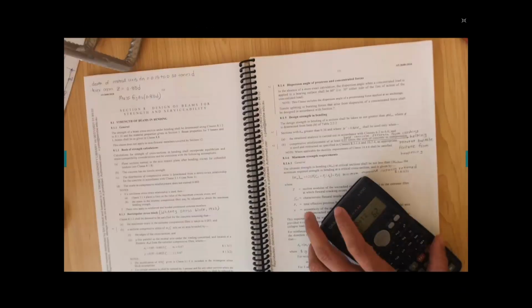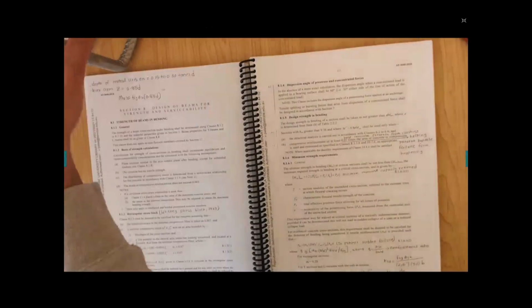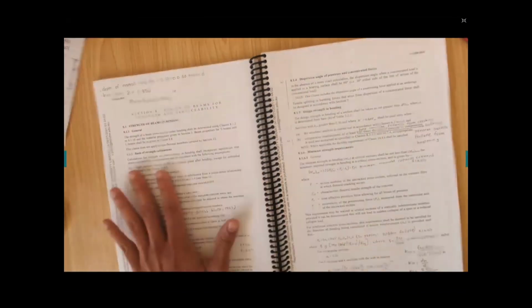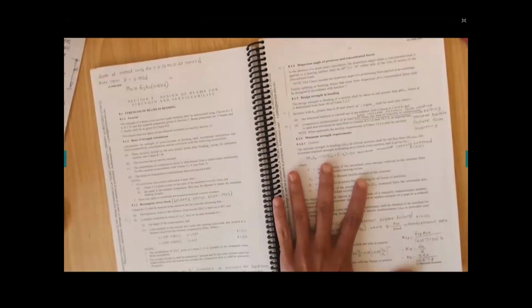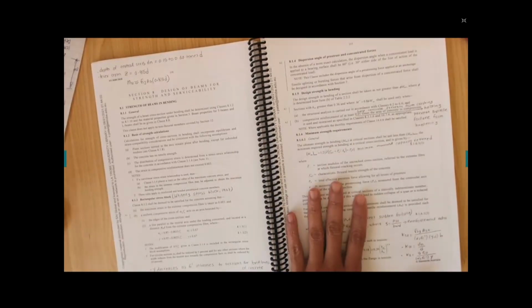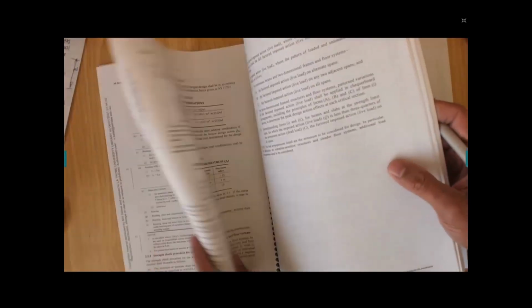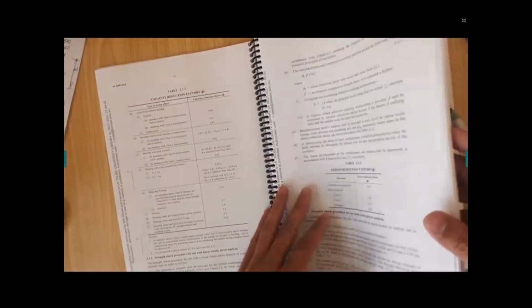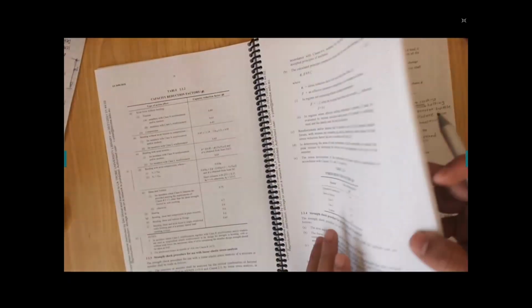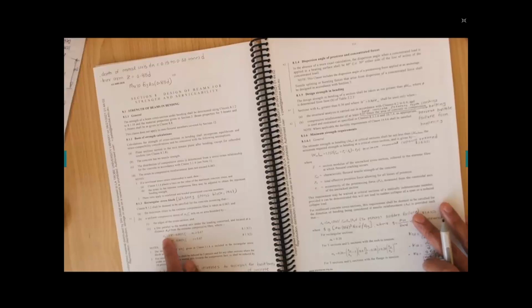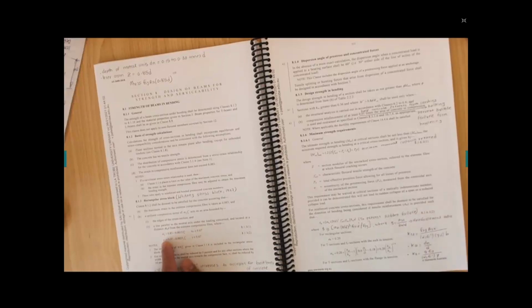By the way, for your purpose, you work out these two. This is a bending one, and then you need to use this Table 2.2 as well. This Table 2.2 for capacity factors, 0.85 when you have Ku less than 0.36. So I'm talking about alpha 2 and gamma.